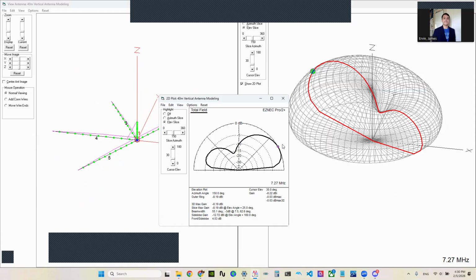I will say, coil shortened verticals tend to lose a lot of power because they tend to have a low resistance in comparison to other kinds of antennas. I guess how to put it, they have a lower radiation resistance because they're electrically smaller compared to a proper quarter or full or half wavelength, right? And so you have some amount of radiation resistance in your system, and you have some amount of ohmic resistance, which is resistance in wires, resistance in connections. And if you look at a ratio of ohmic resistance to radiation resistance, then you get kind of an efficiency of the antenna, right?